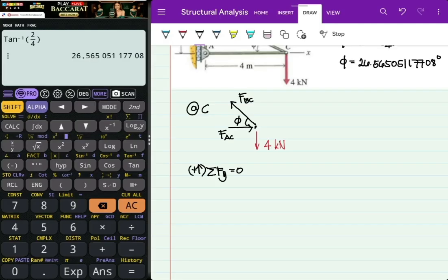It's because the only given force at joint C is 4 kN in the vertical axis, so if we do force summation in x, we will end up with two unknowns. So better to start with the coordinate axis where there is a given value.